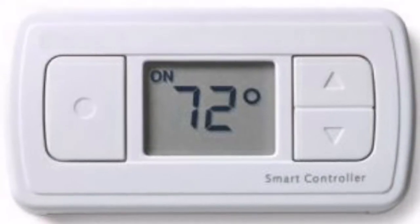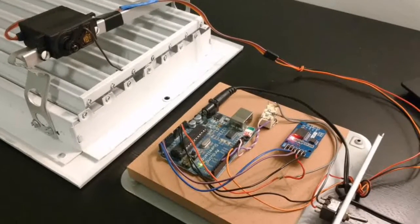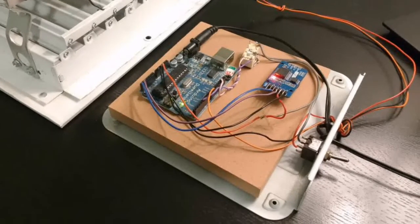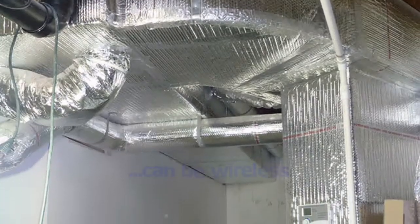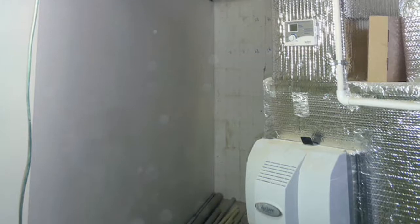With this system, a thermostat is installed in every room, and every register is replaced with a motorized register which opens and closes depending on the room temperature. Either a tube or a wire runs from each register down inside the ductwork to the mechanical room, where it exits the ductwork and is connected to a special zone control panel.